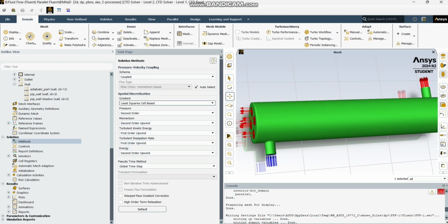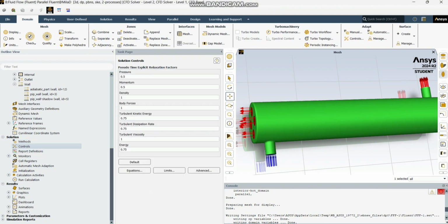As you see here, there are solvers. Momentum is solved with the second order equations. For pressure you can use QUICK, it's more precise, or PRESTO, it's quite precise. And also this in the controls is related to your iteration. The under-relaxation factor completely affects the iteration procedure. I'm not going to change this.